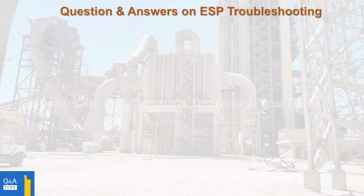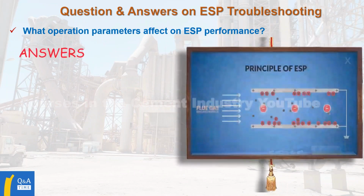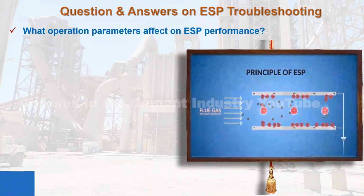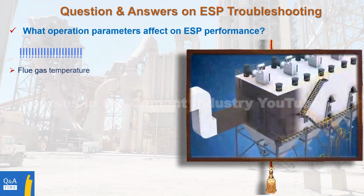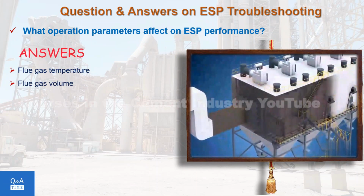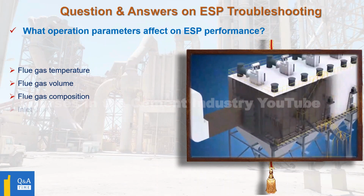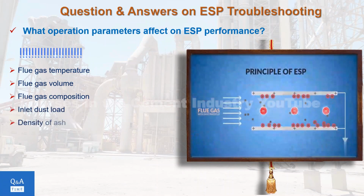Question 13. What operating parameters affect electrostatic precipitator performance? Answer. One. Flue gas temperature. Two. Flue gas volume. Three. Flue gas composition. Four. Inlet dust load. Five. Density of ash.